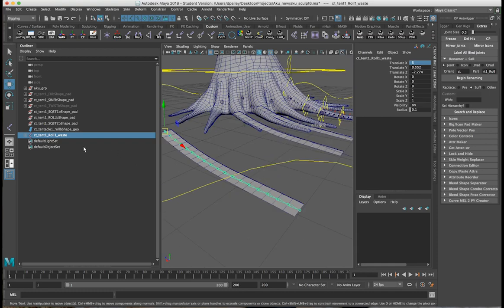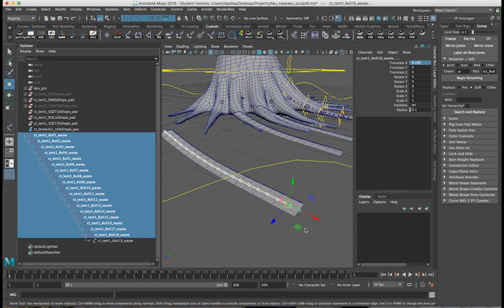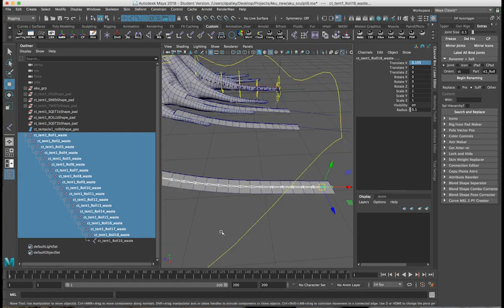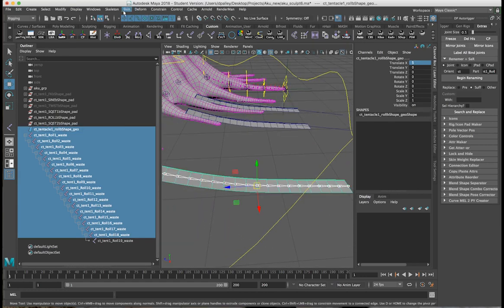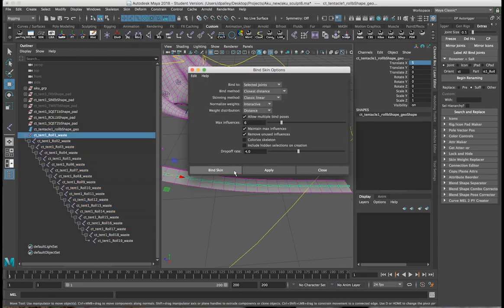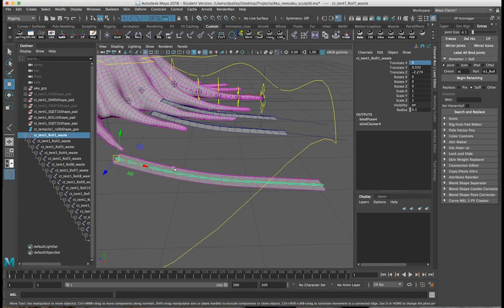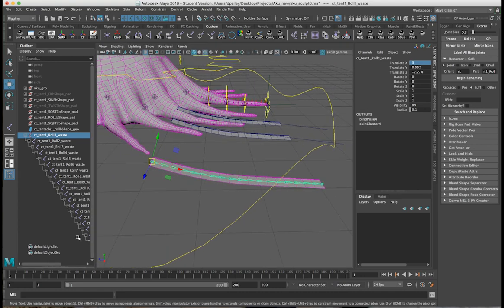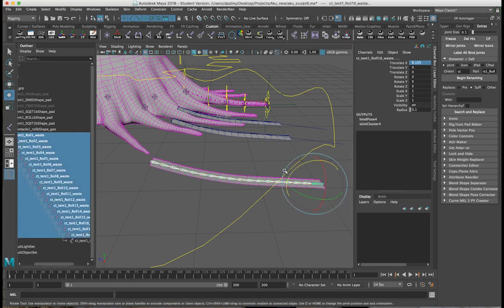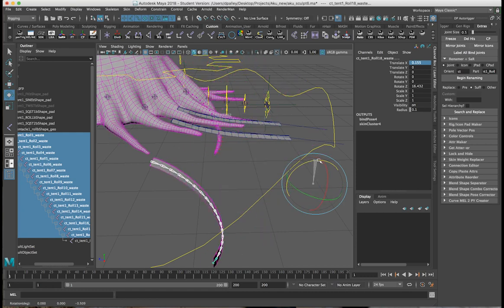And we are going to do the test bind as well. So I'm going to select all the joints except the N1 for the binding setup. And select the geometry. And we go to skin, bind, skin. Default settings should be fine. So let's test it just to make sure everything works properly. So I curl these. There you go. So you see it's affecting the geometry there.